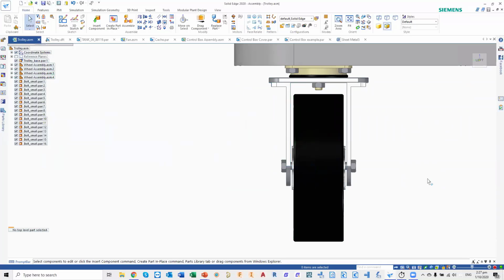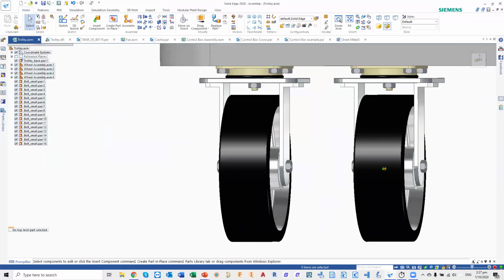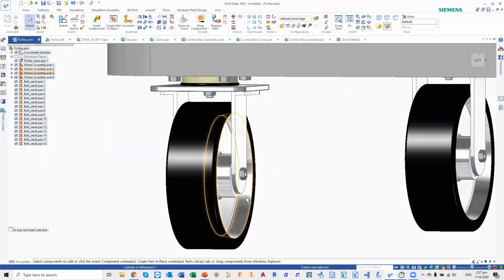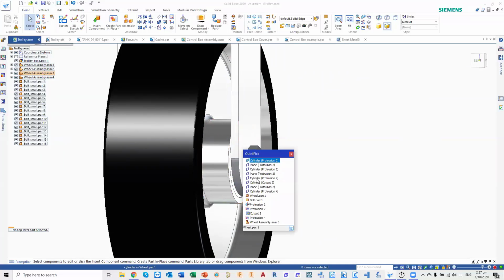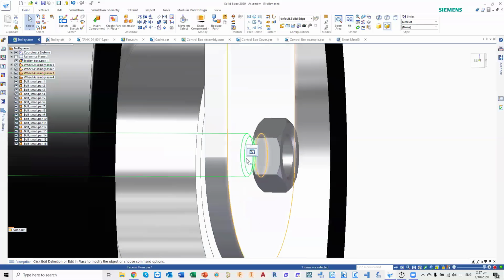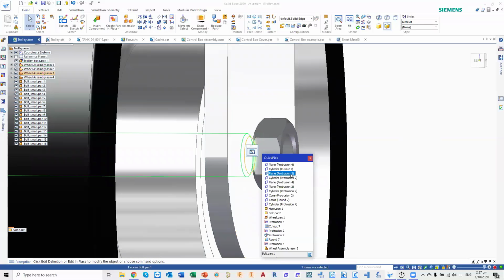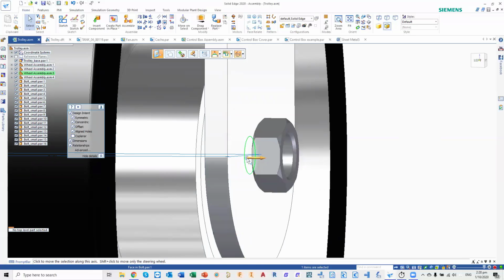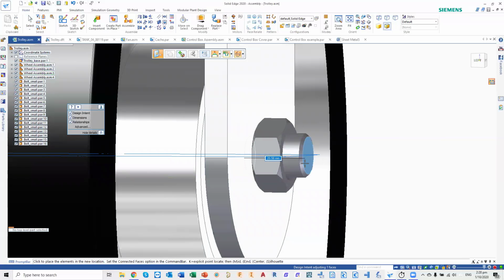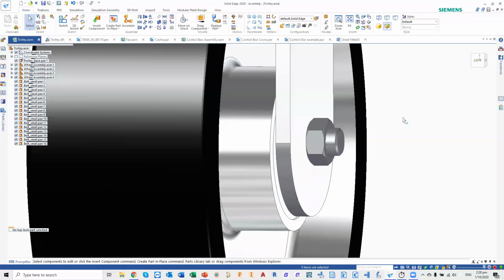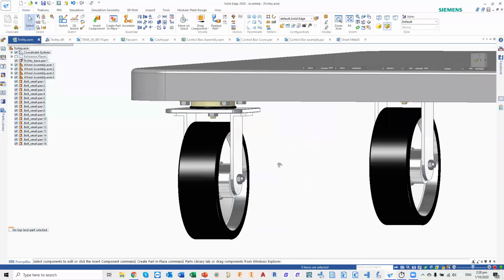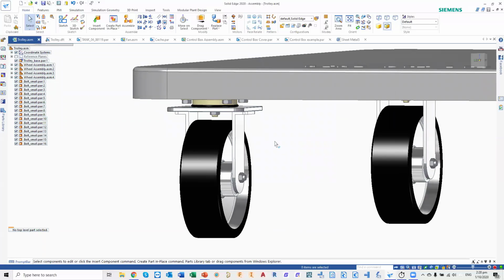Okay, now after editing the size of the wheel together with the bracket, the bolt we need to change as well, right? So I just need to select the bolt here, and then select the surface, then just drag it out by 20 mm. Okay, and this will complete my changes to the wheel together with the bracket and the bolt.